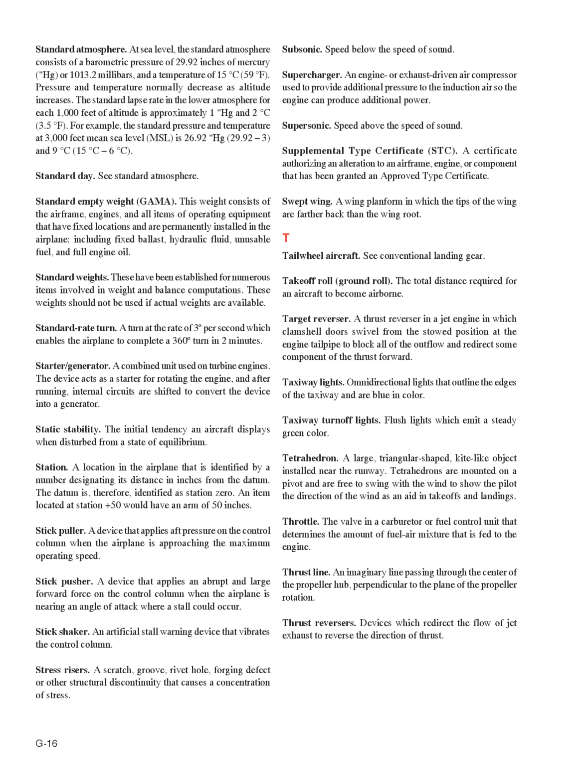Starter/generator. A combined unit used on turbine engines. The device acts as a starter for rotating the engine, and after running, internal circuits are shifted to convert the device into a generator. Static stability. The initial tendency an aircraft displays when disturbed from a state of equilibrium. Station. A location in the airplane that is identified by a number designating its distance in inches from the datum. The datum is, therefore, identified as Station 0. An item located at Station +50 would have an arm of 50 inches.